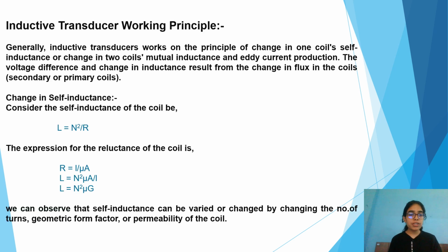Now, the working principle for inductive transducers. Generally, inductive transducers work on the principle of changing one coil's self-inductance or changing two coils' mutual inductance, and eddy current production. The voltage difference and change in inductance result from the change in flux in the coils, secondary or primary coils.